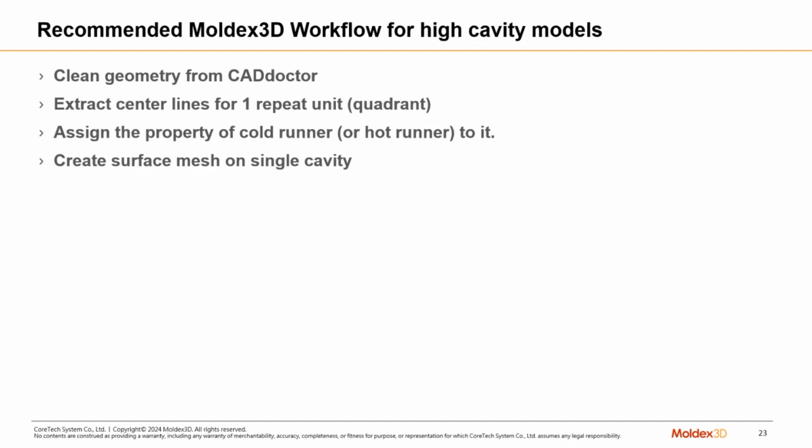All these steps we're going to look at in a picture, in a more visual format, in the upcoming slides. I just wanted to run through what the steps are, so anybody who gets a copy of this presentation has them, and whenever they have a multi-cavity tool, they know what to do step by step. Use the mirror function to create the half or the quarter cavity.